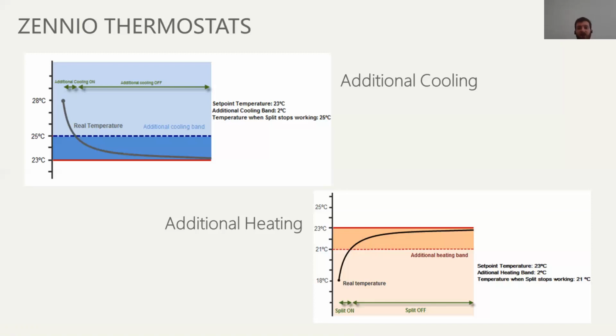With AC, for example, or with 2-point hysteresis in a room, in the summer, if it's a very hot summer, you will see it's turning on, turning off, turning on, turning off, and you will be getting that temperature difference depending on the 2 points on the hysteresis you have defined.